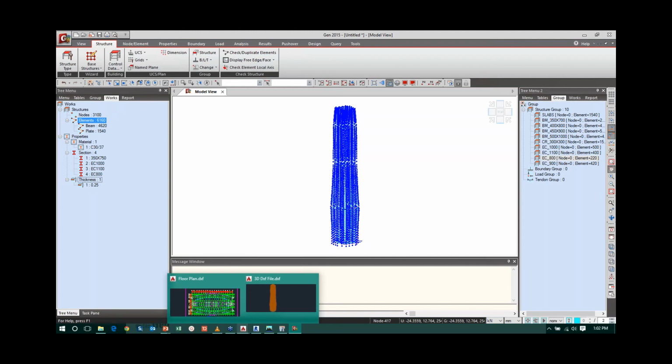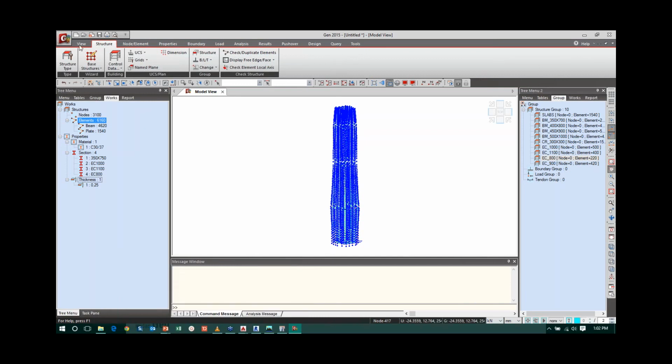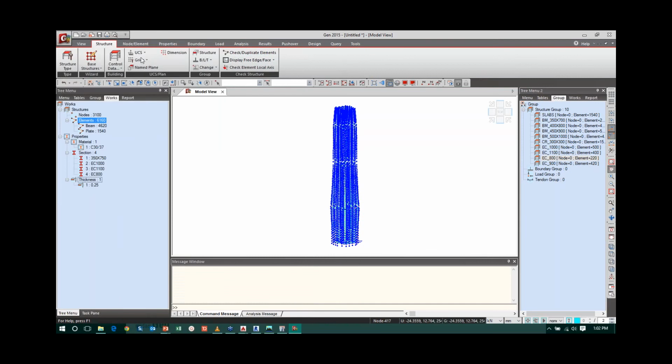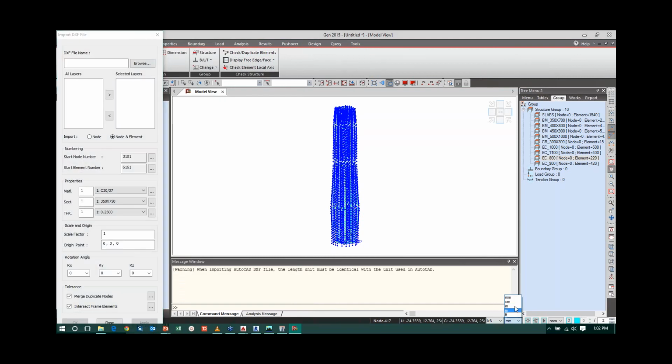One is from Mr. Levi Cuno: Why is the Z coordinate in meters while the dimensions are in mm? Sir, when I did the import, the unit system was in meters. So I entered the Z axis in meters, say 4. Later, before import, I changed it to mm. When I change it to mm, you can see the value also changes to mm. It automatically converts to 4000.